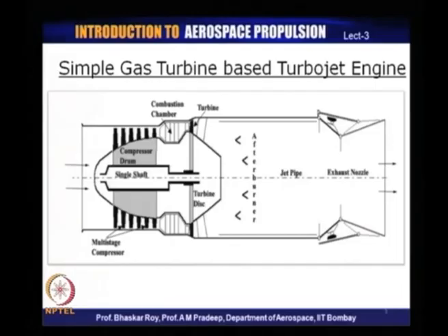As you can see, once the air comes in through the intake, it has nowhere else to go. It has to go through all the components and exit through the nozzle. It has nowhere else to go. So, the amount of air or the mass of air that comes in here would be approximately the same. With the addition of fuel, there will be a little more that exits finally from the propulsive device, that is through the nozzle, and that produces the change of momentum, and this change of momentum produces the action, which of course, as we have discussed, produces the reaction which creates a thrust.